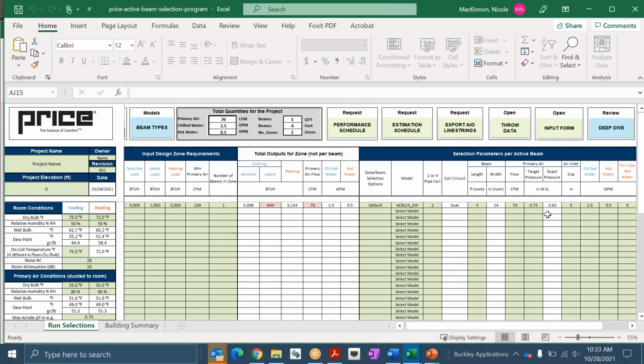So that's giving you a lot of capacity out of the water coil, and really playing off the GPMs that we added, and making that water coil more efficient, or having a larger capacity. So that's why you'll see a larger swing on the air side. Changing the GPM may not have a huge effect, but it will have a smaller effect and have some effect. So we like to max the water side out first, just to stay as efficient as possible. You really want to use the water system for as much of the load as you can get away with, and lean on that and try to reduce your fan energy. That is the main goal of chilled beams, to stay energy efficient. So that's why we'll sacrifice the water first and add some more pump energy, and then bump the air side up as we need to.